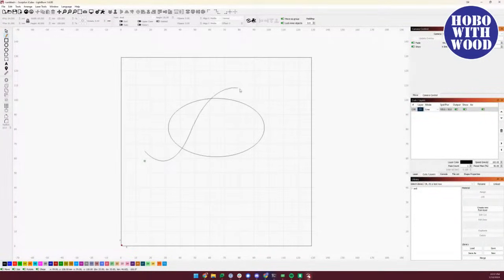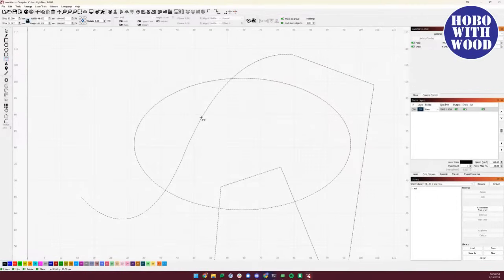But if you select these and go into Node Edit, you can hover over something and hit T, and it apparently doesn't work at the time, because you're in tab mode. You're right, I clicked the wrong one. Okay, so if you hit T, it will trim. Tab was the other thing that I spent a lot of time on.